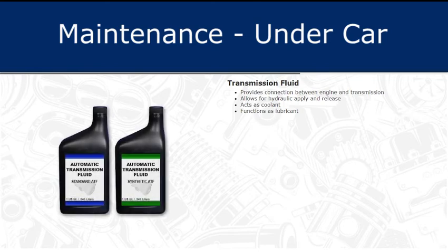Transmission fluid provides a connection between the engine and the transmission. It acts as a hydraulic fluid for the application and release of clutches and bands. It also functions as a coolant and a lubricant for the transmission components.